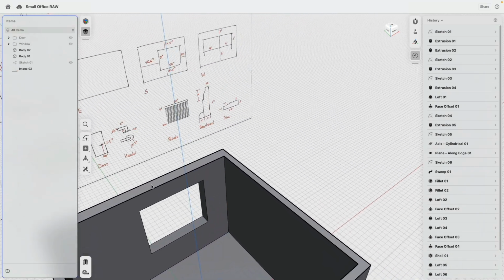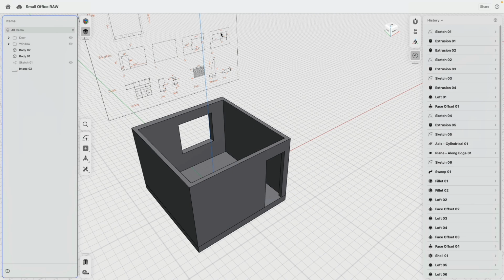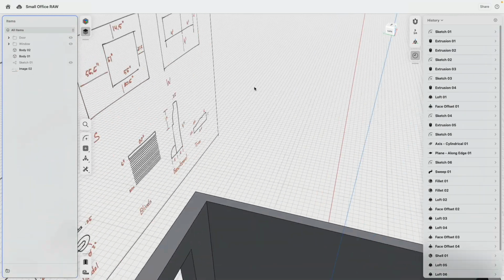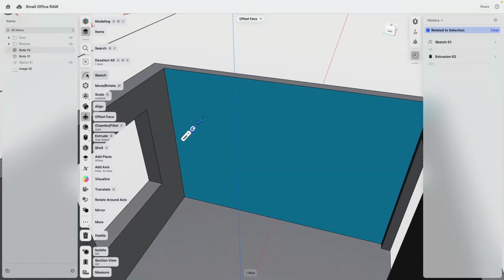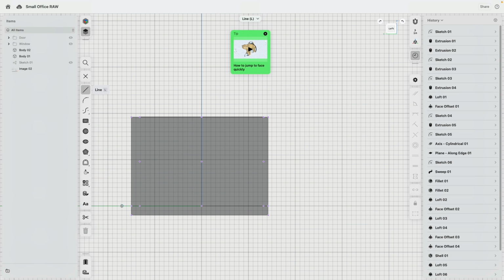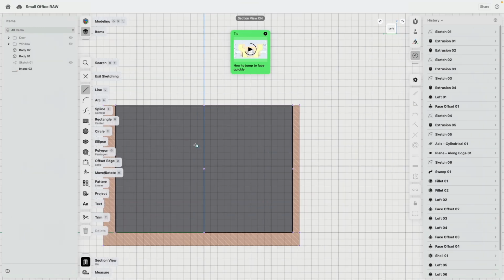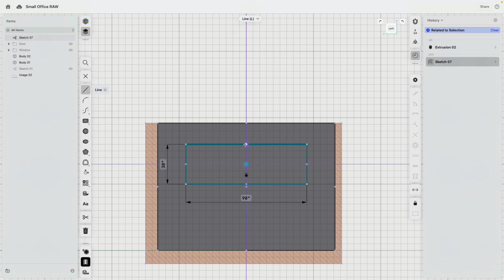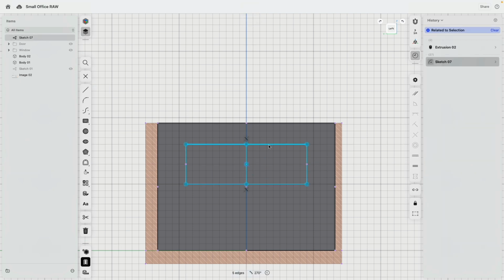Let's take a look at the pinwall. So it is 2 feet, 4 feet, 4 feet, 2 feet, and 4 feet. Okay, very good. Same process again. I click sketch. Then it goes to the plan view, section cut, so I don't see that thing. These are essentially 2 elements. So I'm drawing here just a rectangle and then draw a vertical division line. This is actually 24 inches, now 2 feet, and then that is 8 multiplied by 12. There we are.